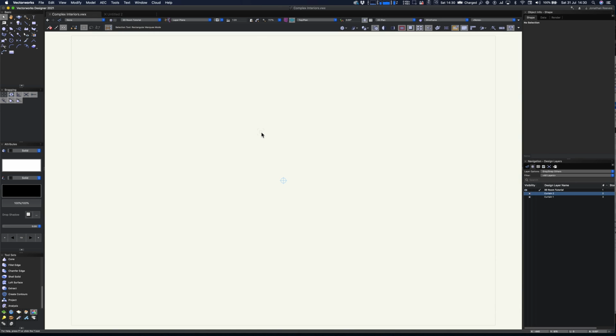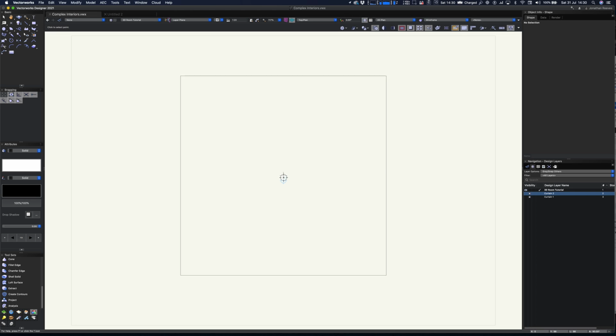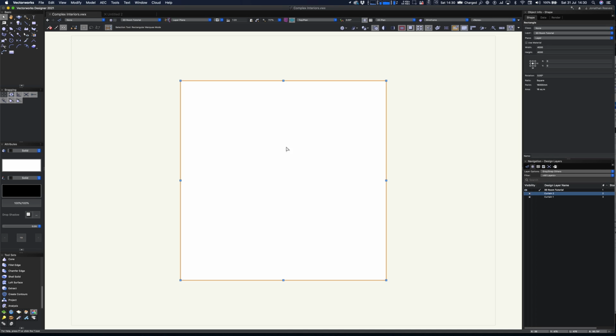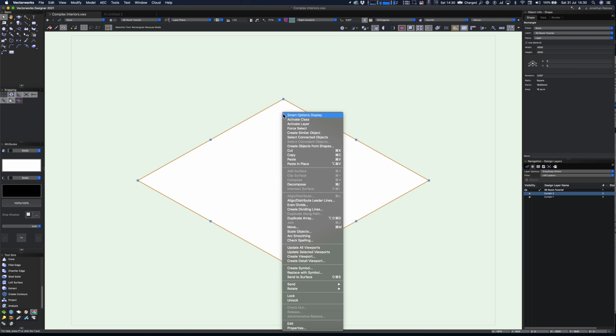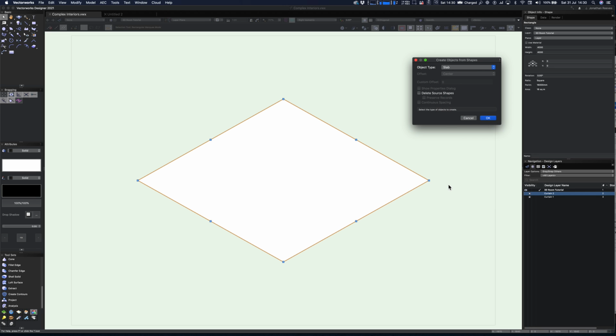We're going to set the scale to 1:20 scale. It's quite a nice scale to work out for a single room. And I'm just going to click onto my rectangle tool, double clicking and type in a room size of say 4 meters by 4 meters. And just click on that central point just to start off. So I'm bang in the middle of the paper. Always like to work in the center of the paper, so when you change the view, it's always right in front of you.